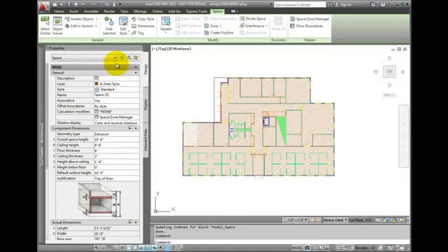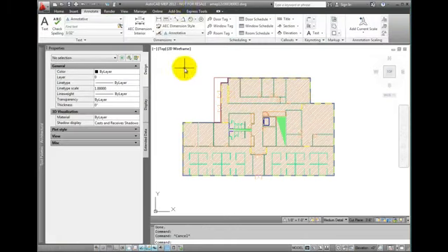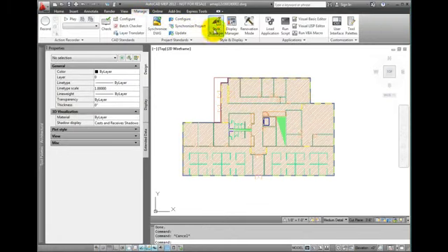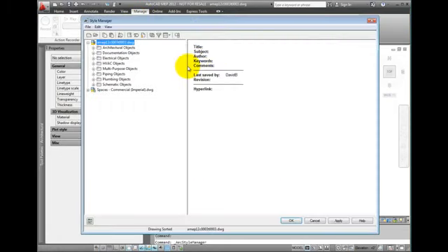Key space properties that are created upon generation include the layer. This is based on the layer key style that is associated with spaces. Out of the box, it complies with the National CAD standard. Style. You can have a variety of styles, which control all examples of a space. To import space styles, select the Style Manager on the Manage tab.